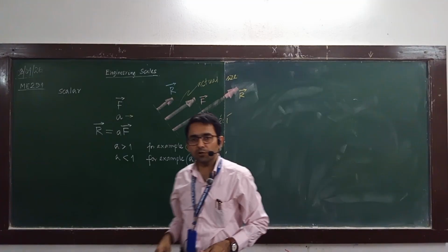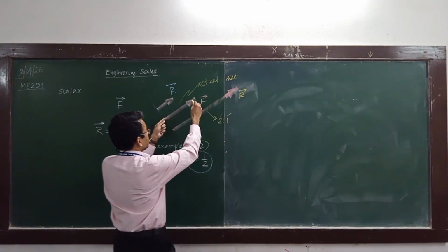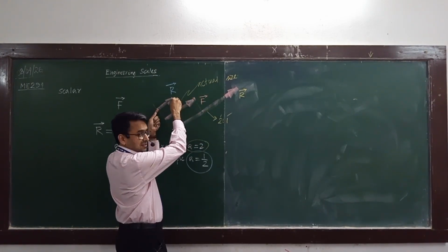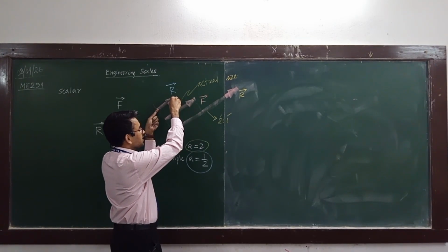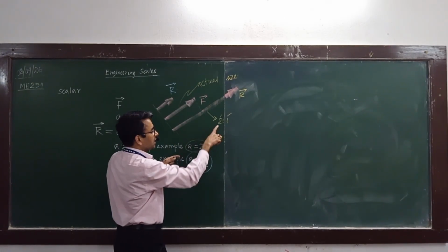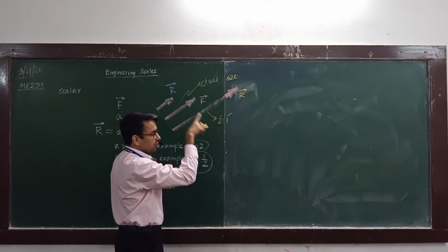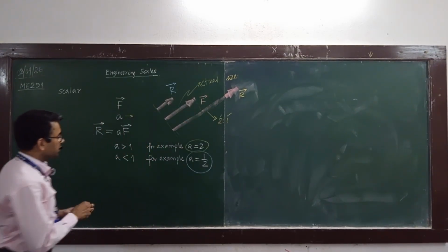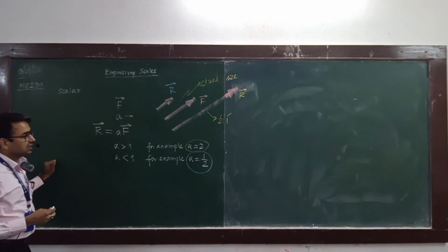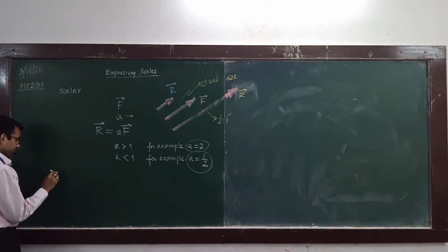Say for example, when you have a car, the actual car is large and the drawing size is less. So in that case, what will be the scale? Half. That is 1:2. When you want to enlarge, then the actual size is less and the drawing size is more. So 2:1. Therefore we define a scale, and we write the scale in terms of a particular name, that is called RF.